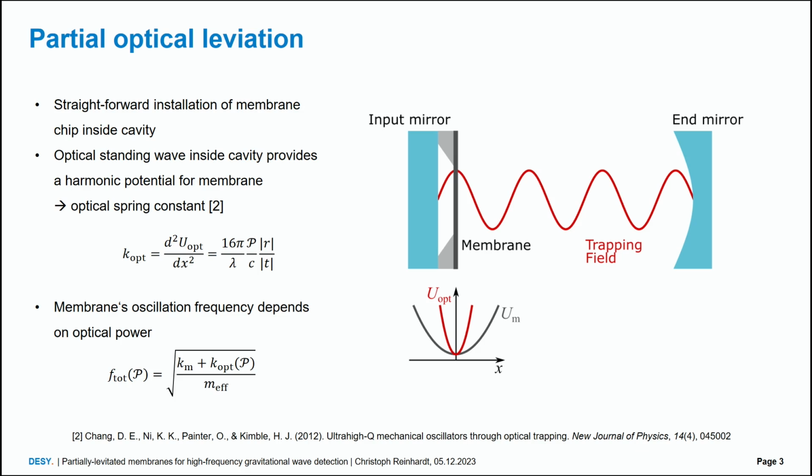And yeah, it should be. As we heard in the morning, to get to a reasonable bandwidth, you need to cool it, because right now you have a Q of 10 to the 12, 10 to the 13, so your line width is extremely narrow. So to get to a reasonable bandwidth, you need to cool it to broaden the line. And at the same time, you reduce the Q factor as well as the temperature. So you keep the force sensitivity, but you increase the bandwidth.